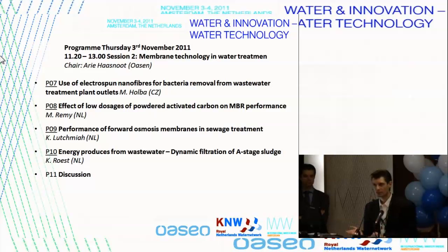And you can collect these organics with an influent fine sieve, for example, where you already collect a lot of organics, the suspended solids. Maybe you can also up-concentrate the sewage in such a way, by extracting so much water, that the concentrated sewage can be digested. But it's all still not yet applied. It's still lab work, so we have to make a lot of steps, and also with the forward osmosis membrane, still a lot of steps have to be taken to make this commercially applicable.